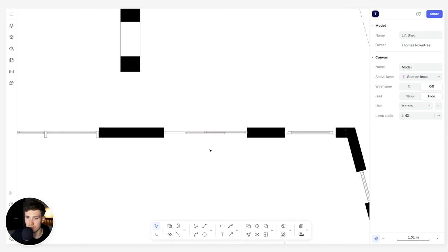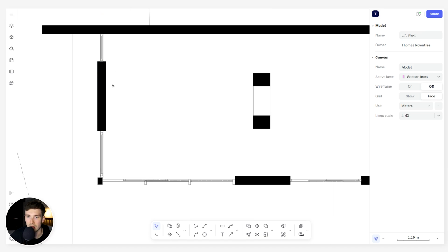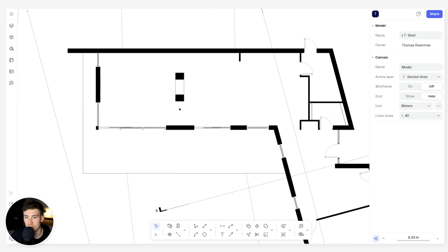And therefore we've got some sliding doors for access to this patio here off the dining room, and then more significant glazing on this end of the building where we have a living space, and potentially this solid wall where we could have, I don't know, a TV or something, where you could have potentially seating around this zone. So we have some solid and void zones where we have glass openings, but then obviously some feature walls just to break up the elevation and give it a bit of a composition.